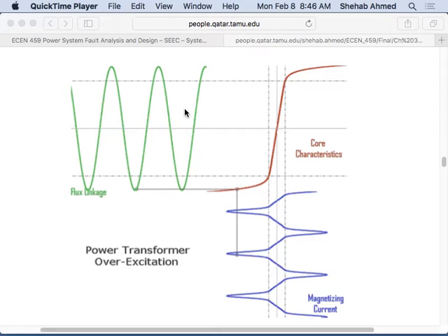So if my voltage is a sine wave, this is a sine wave, but phase shifted with respect to it. I took my flux and said it's equal to mu h. If it's only equal to mu h, that means there's a linear relationship between the flux linkage and the excitation current, which is due to the magnetomotive force, which is this h that I have. If I take a sine wave multiplied by something linear, I will get a sine wave. B equals mu h.